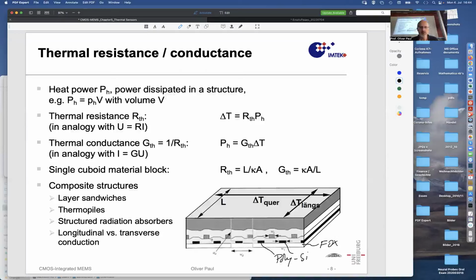Then we have the contact oxide that covers the polysilicon. Those polysilicon structures are not just a little cross section; they are long lines that go along the structure. Above the contact oxide there is a metal 1 line, and that's again a line that goes right from the front to the back of the structure.